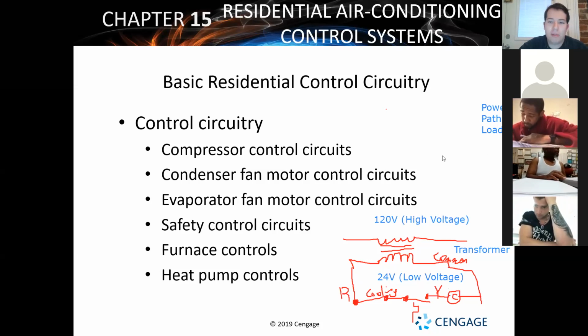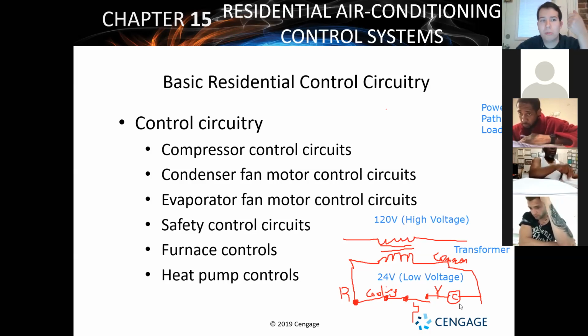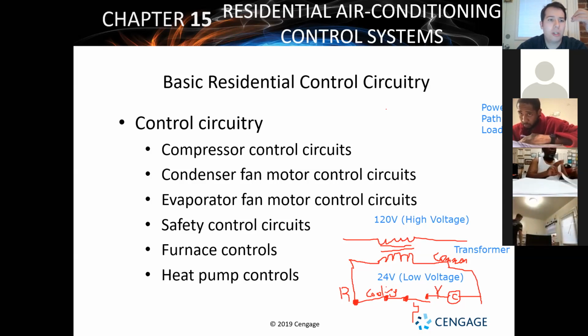It just depends on the manufacturer a lot of times, but typically what you're going to see is that cooling call, they'll have low voltage, send a signal, and then go out through that. Now, along with that, you can have extra switches. You can put switches in series with each other on that low voltage switch, so I can have it where coming from my cooling call through that temperature switch, well, it can go straight to the contactor, or I could make it where it has to go through 2 pressure switches and a temperature switch and another temperature switch,